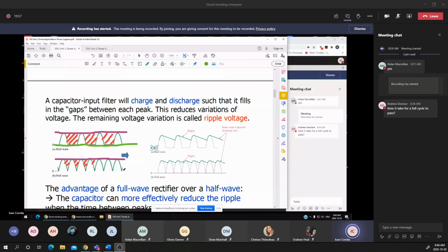That's the output voltage of the unfiltered full wave rectifier. Compare the two diagrams. You notice that at this point, instead of having a full ripple or a maximum ripple, the difference between the maximum voltage and the minimum voltage, now we have the output voltage between two limits.